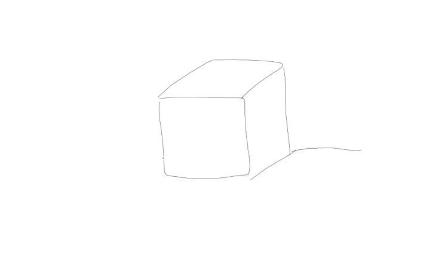So why a cube? Because if you look at your cube, every single edge of your cube can be made to coincide with one of your coordinate axes. Meaning, if I define my cube like this, then I can very easily make that my x-axis, make that my y-axis, and that my z-axis. And what that means is on this cube, I've got 6 different faces. And if I have forces that are acting perpendicular to each of those faces, those forces end up giving me stresses in the x, y, or z directions. Does that make sense?